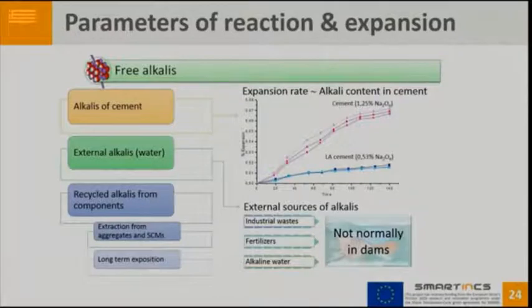In this case, we need to test the aggregates in order to estimate the alkalis leaching from the aggregates or other constituents of the concrete, like supplementary cementitious material.